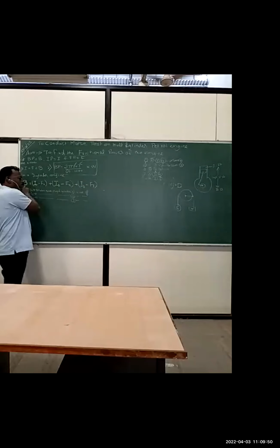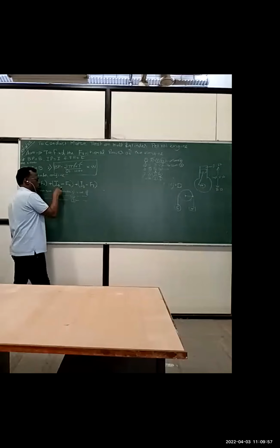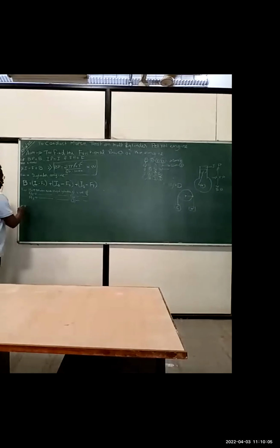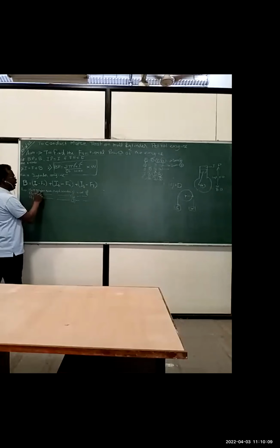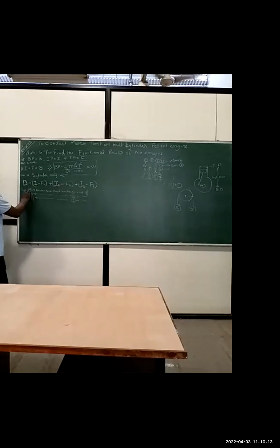So total brake power produced is equal to the brake power produced by cylinder number 1, plus cylinder number 2, plus cylinder number 3. Okay, I think this much is very clear. Now, moving ahead, what I will be doing is denoting by B1 the brake power when the spark plug of cylinder number 1 is cut off.